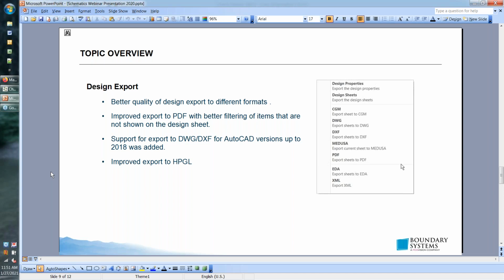So while they are not outputting to a 2020-2021 version of the AutoCAD DXF DWG standard, they're outputting to something pretty recent that should be openable in any version that is newer than what they're supporting. Now, that being said, I assume the restrictions in the AutoCAD space may be similar, that if this were to be output to the newer version standard, a user on the AutoCAD side receiving your export that might be in a 16 version or something like that, I cannot speak explicitly to their ability to open that more newly saved file out of Creo.